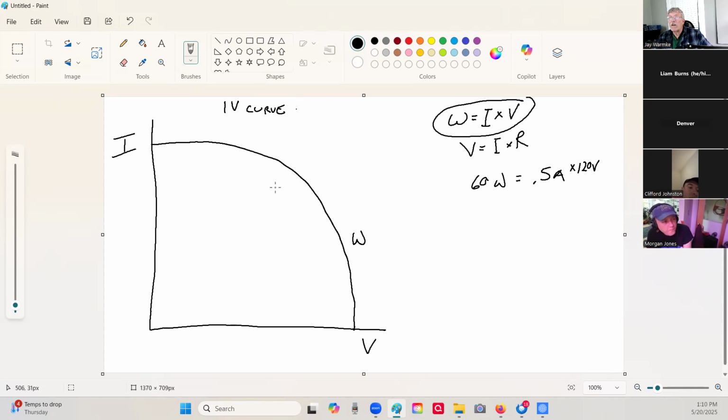Now this IV curve that you're given, and you don't have to calculate any of this, it's all given to you by the panel manufacturer. This is under standard test conditions. So the curve that you're given is under standard test conditions. And what are the things that are required for standard test conditions to exist? This time I'm going to require somebody to unmute and give me the three conditions that make up standard test conditions. I'll give you a hint. One's about temperature.